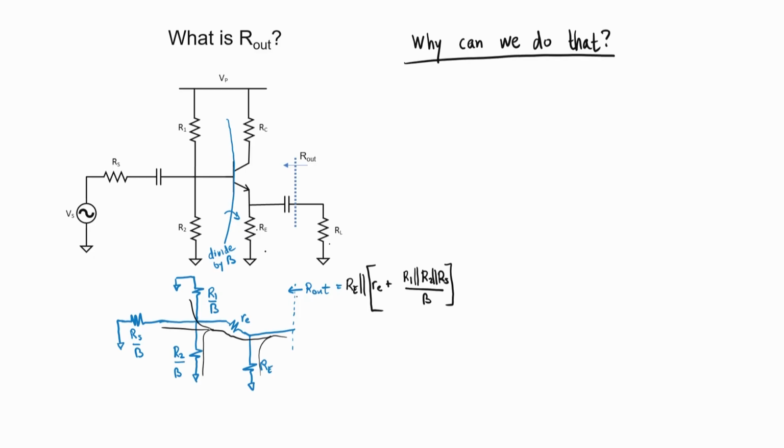I want to replace our circuit diagram and the transistor with a small signal equivalent model. To the left of the base, we have resistor R sub S, and we have 2 resistors in parallel with one another. We now reach the base of the transistor. AC base current little IB is going to flow into the base. We have some things connected to the collector, and I'm going to ignore them. What the transistor does is it creates a collector current by multiplying beta times the base current.